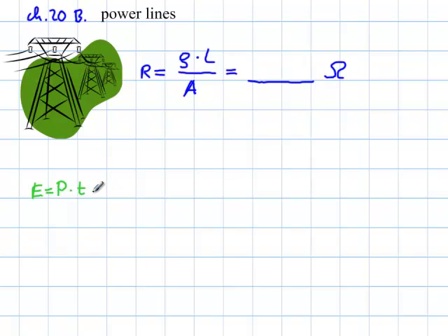And in the previous problem, I wrote this as electric current times voltage times time. And now they give us the resistance in the wire, so I'm going to use Ohm's law and plug it in, that voltage equals current times resistance. So another I times R, which makes this one here an I squared R times time.